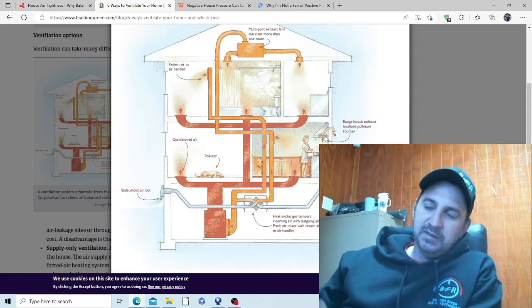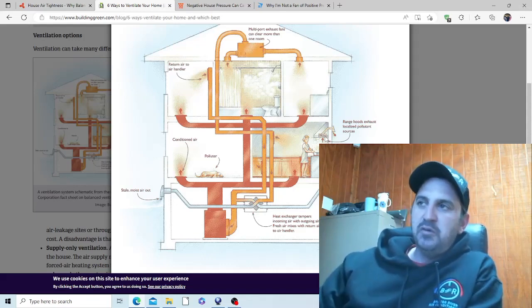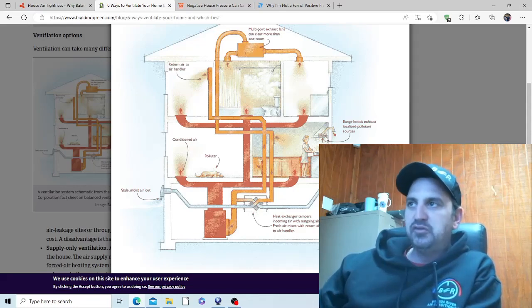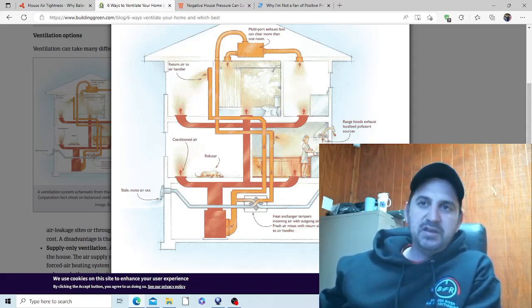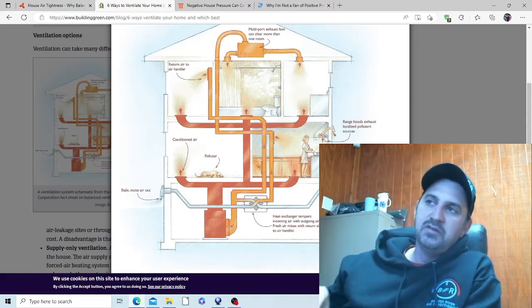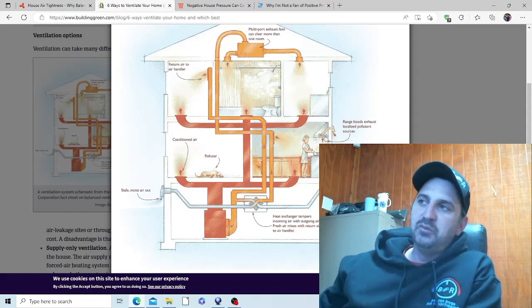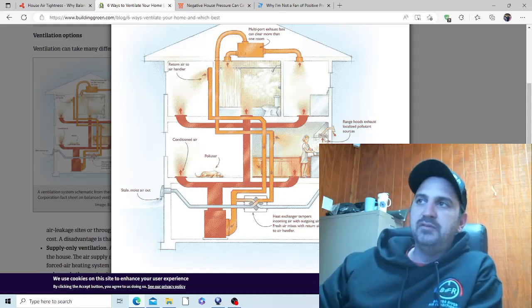So there's dehumidifiers and ways around humidity in these homes, and we do use dehumidifiers to help supplement our HVAC systems in different homes. But for the most part, if you can reduce that moisture with a good fresh air system, you will be much better off.